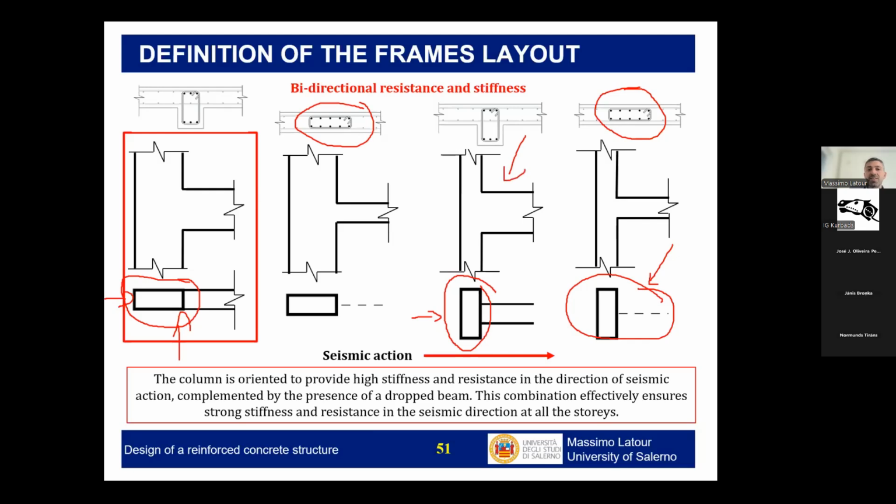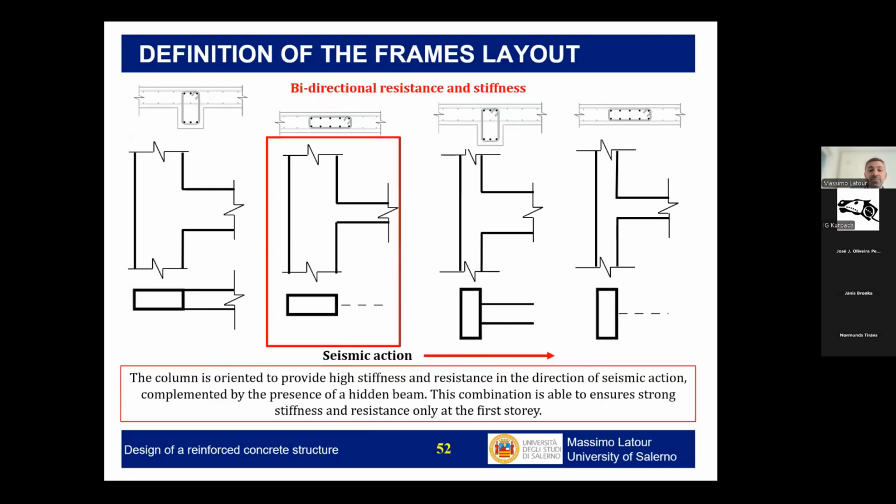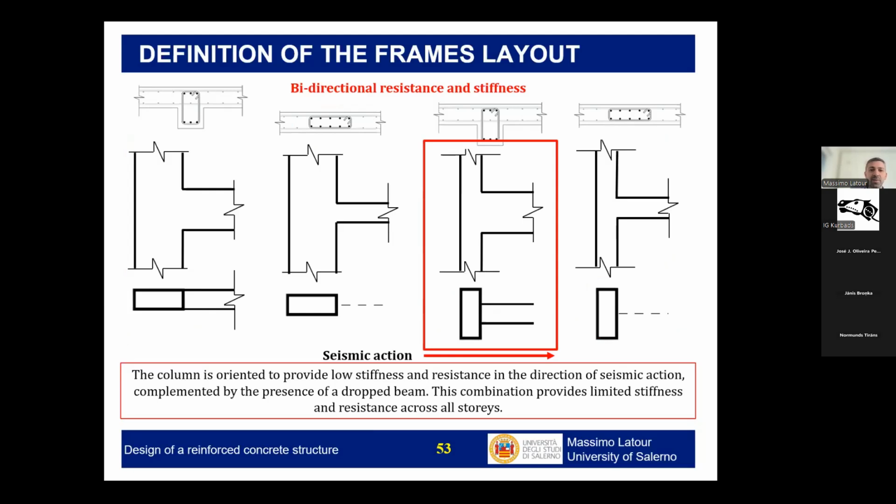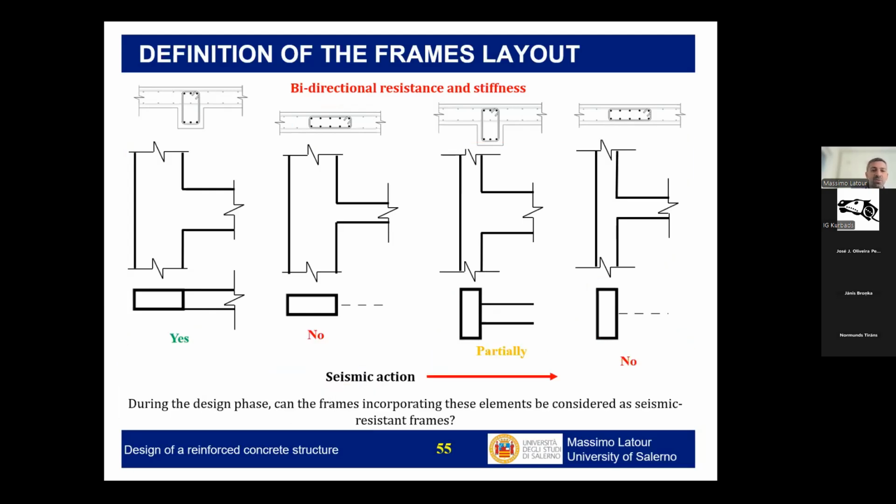In this third case, normally I don't have a very big seismic resistance. Mostly I will have just a contribution in the second and third case for the first story. So for the first story, if the building is not too high, maybe I can still have some contribution. But if the building has a higher number of stories, the contribution will be very, very limited. In this slide I have some explanation which I just gave you.